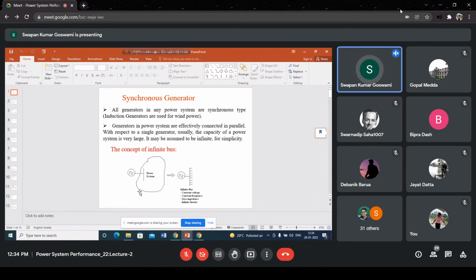So constant frequency is the frequency of this bus. Obviously, a bus cannot have any frequency, because a generator can have a frequency. Actually, this bus is representing the total capacity of the generators of the power system, the accumulated capacity of the system, which is generated by synchronous generators and is represented by a single generator, and the frequency of that large generator is constant. This is what we want to mean here. So constant frequency means that the generator representing the total capacity of the system to which this bus is connected is actually behaving as a constant frequency generator.